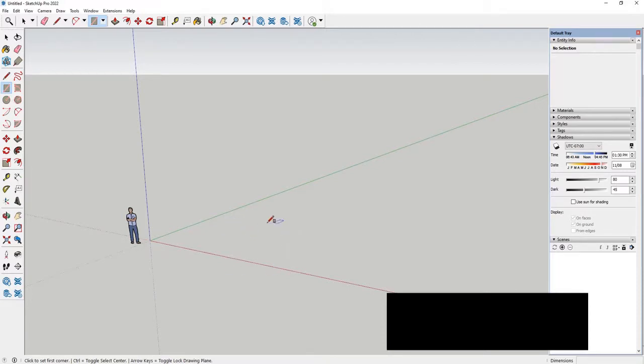So let's go ahead and specify a point anywhere on here. Let's left click. Now as you can see over in the bottom right here, you've got these active dimensions that are changing as I'm moving around. So in this case, why don't we go ahead and make it 6,000 millimeters or 6 meters wide by 9,000 millimeters or 9 meters deep. So I'll pick the rectangle tool, left click to specify a point, and begin drawing.